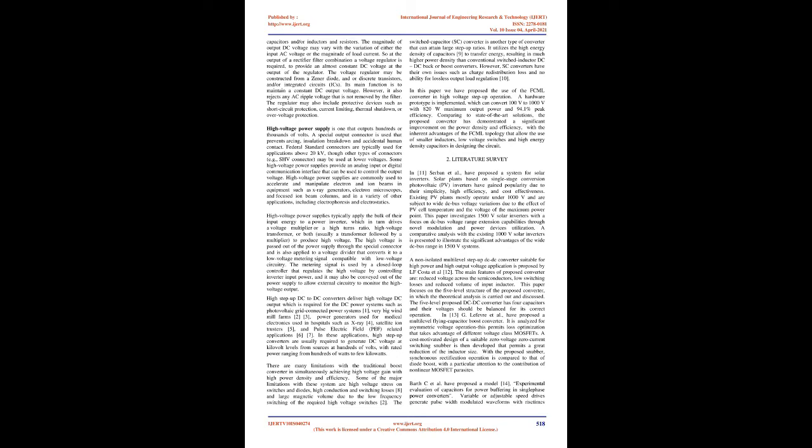Federal standard connectors are typically used for applications above 20 kV, though other types of connectors, e.g., SHV connector, may be used at lower voltages. Some high-voltage power supplies provide an analog input or digital communication interface that can be used to control the output voltage. High-voltage power supplies are commonly used to accelerate and manipulate electron and ion beams in equipment such as X-ray generators, electron microscopes, and focused ion beam columns, and in a variety of other applications, including electrophoresis and electrostatics.